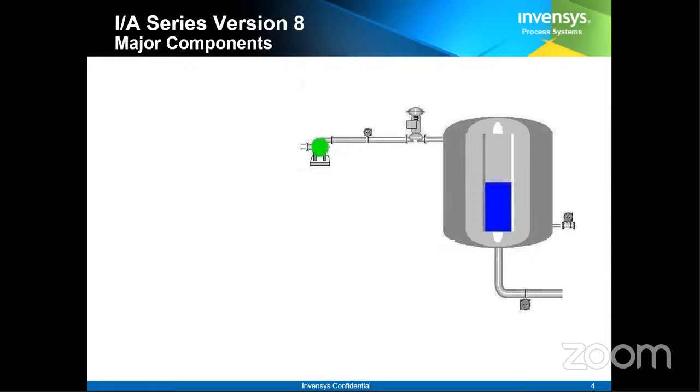When I say controlling, in industry it is categorized into two different types: continuous control and discrete control. In a continuous control system, the control output will be continuous, like an analog output. If I am operating a particular valve, I will not operate it as on or off; I will operate it at 10%, 20%, 30%, 40%, 50%. That is called continuous control output. But if I am simply making the valve on and off, that is called discrete control.